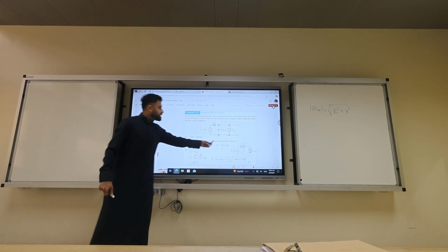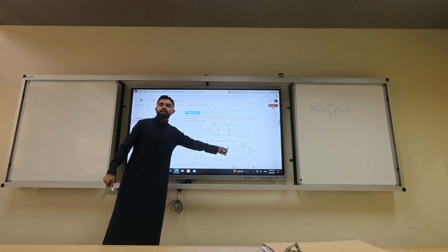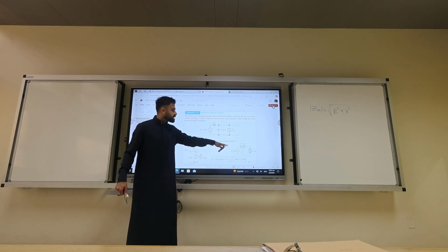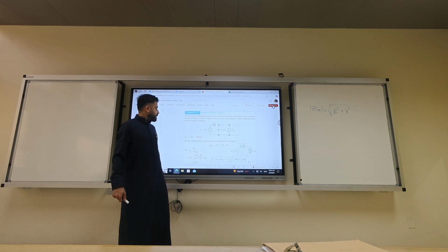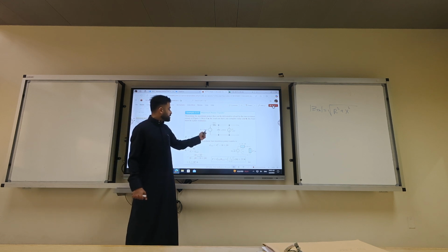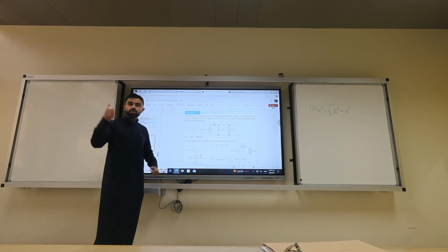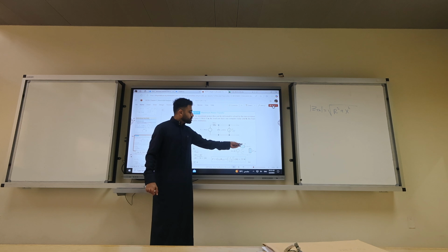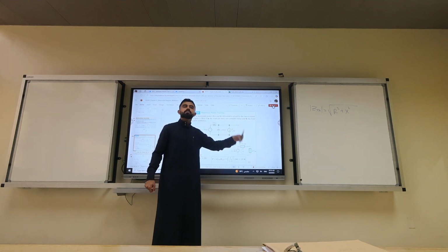Looking at this example, Z Thévenin was what? 50 plus j50. What is the load at which the maximum power transfer occurs? 50 minus j50. And this is if it was only complex. And what is the current? The current is V Thévenin, which is 100 angle minus 90, which we calculated last time, divided by 50 minus j50 plus 50.